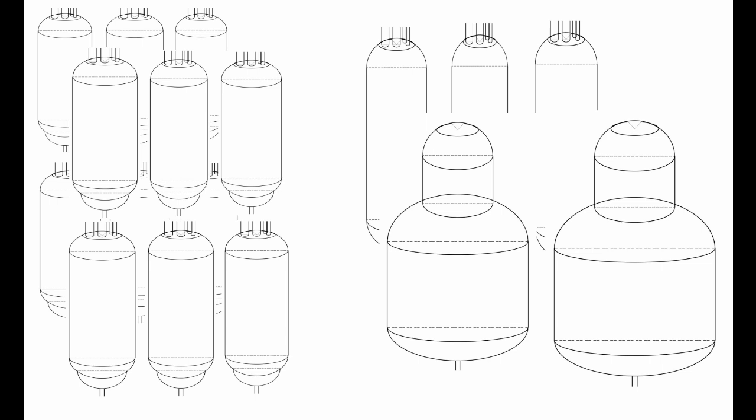First, in contrast, in this design version, the digester bioreactors are deployed to operate sequentially to enable limited continuous process, albeit a pseudo-continuous integrated process of biological reactors, which are anaerobic digesters bioreactors, with the digestate of each digester being ground up into puree and fed into the fermentation bioreactors, where the nutrients are utilized by the microorganisms of choice, resulting in the fermentation of bioethanol or biobutanol as per the design specifications, and that gets separated from mixture of alcohol plus microorganisms before being fed into the biorefinery equilibrium stills for batch distillation.